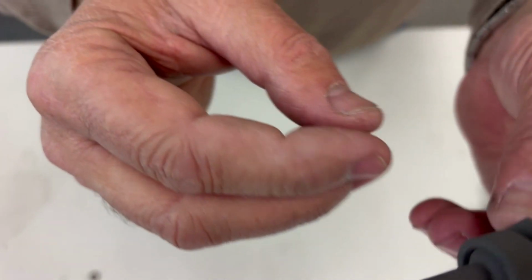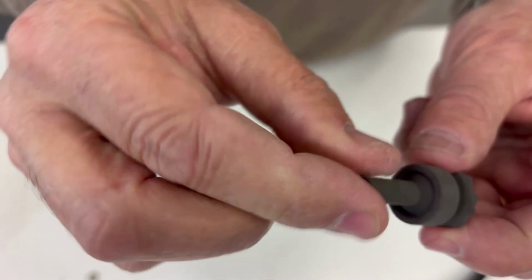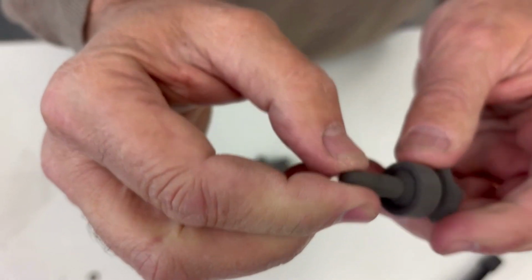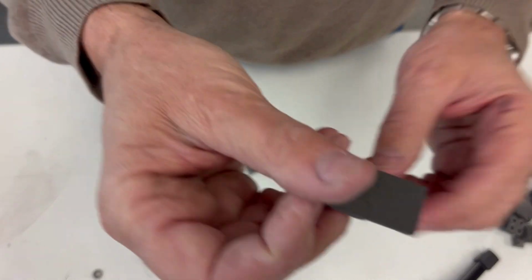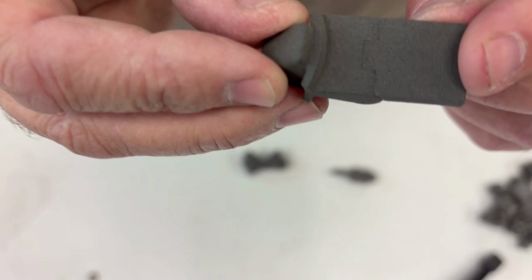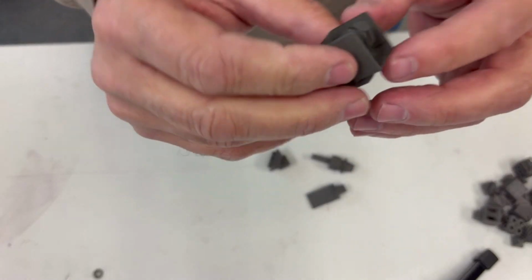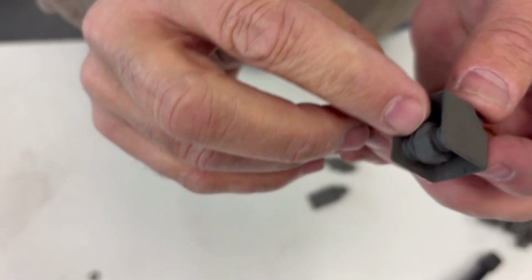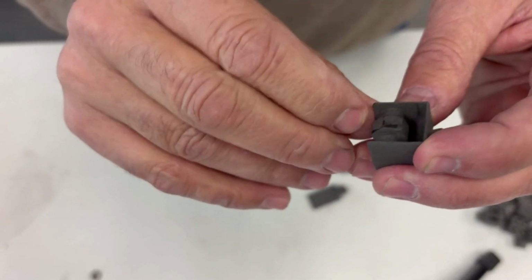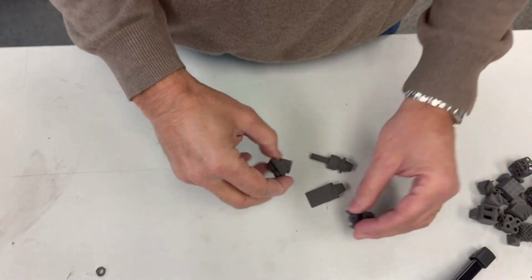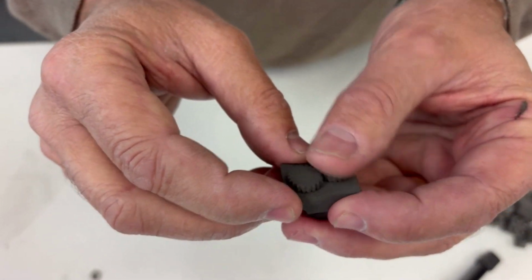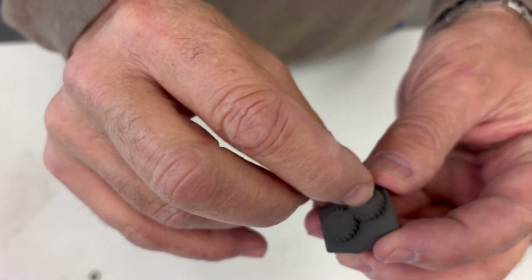One was a ball on the end of a stick that fit in a cup that should have rotated. I refer to it as the ball cup part. Another was this hinge where I believe I measured less than 0.3 millimeter tolerance gap between the rotating parts. Another was this threaded bolt that should have moved up and down, and the gap in the model was also less than 0.3. And lastly, these gears, which the model shows only like 0.2 millimeter clearance.